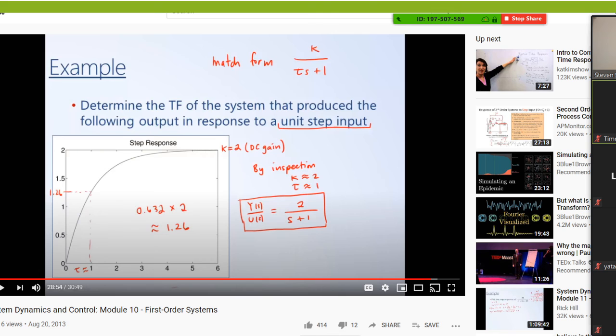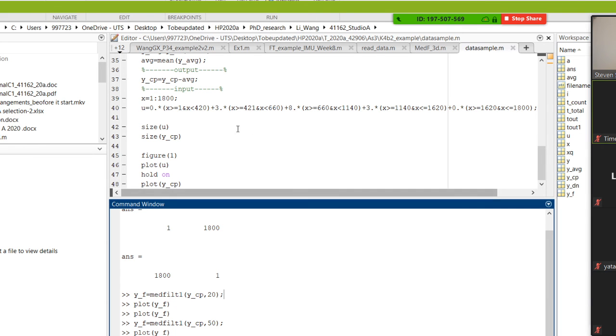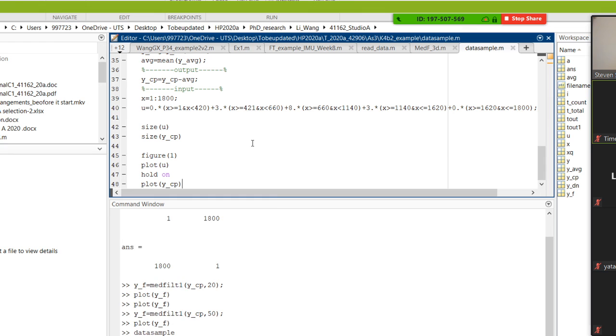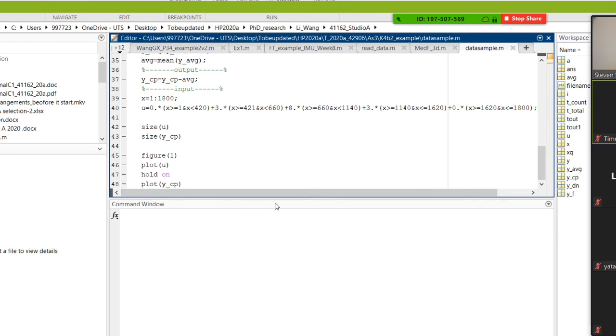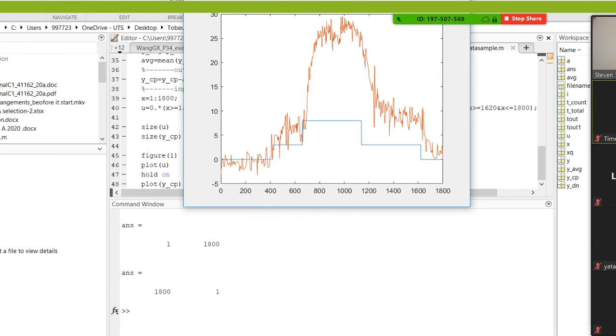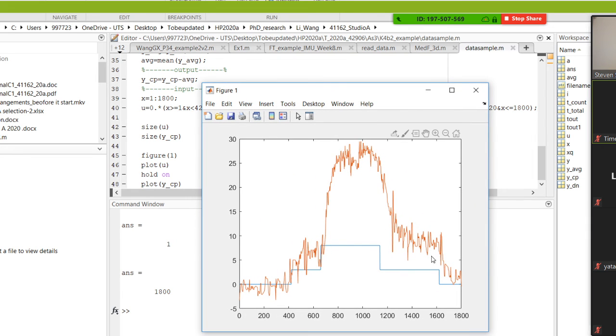The one I already drew here, I think if you look at the original figure. I will give you this data, and then you need to find the model. Here, there's one step, but this step you can neglect. I'm only interested in what's the time constant here and what's the gain here. So in that case, you have a step from here to here, right? So it's a step response, so it's first order. You can use any order, but I think maybe first order is okay.